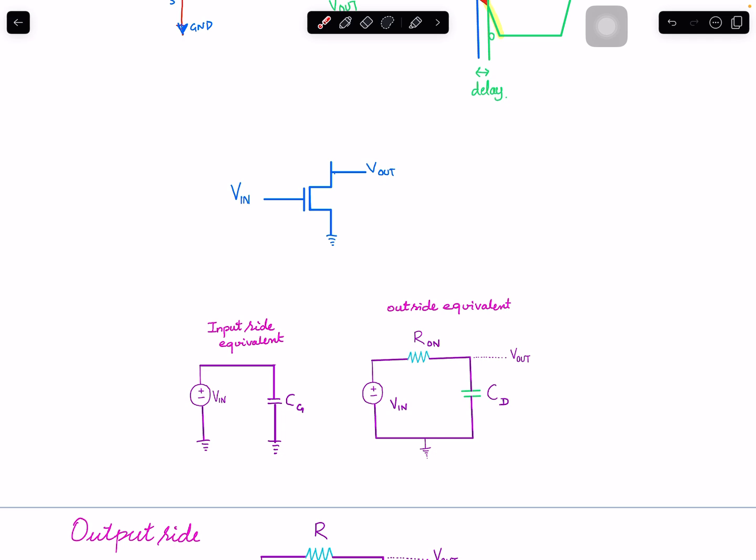On the output side, it's a voltage, the impact of that input voltage that you applied at the gate. It's like a Vn. Now in the NMOS case, it's always inverse logic, so maybe I should put minus Vn. Just assume it, without worrying about polarity. So it's like a voltage source that is driving this from this side. It's like a Thevenin equivalent voltage source, if you remember Thevenin and what was the other one? Norton. So you have a voltage and it has a series resistance.